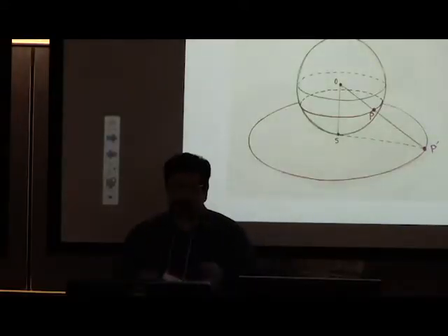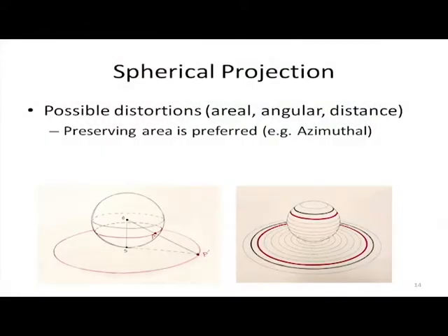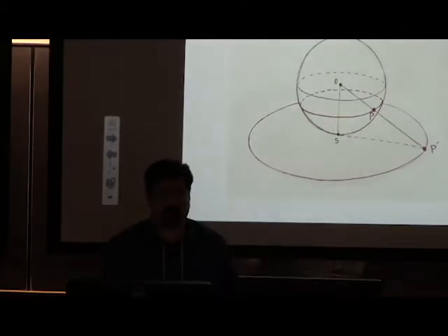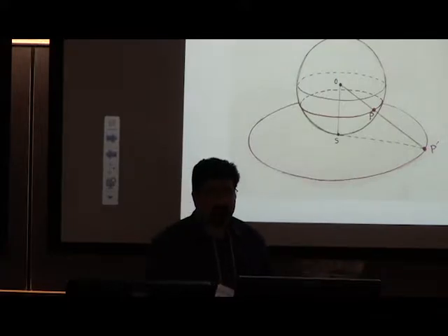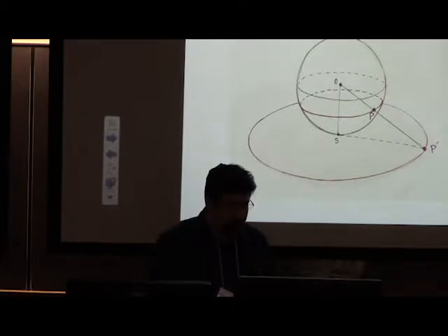So there is potential distortion of area, angle, shape, distance, and direction, and whatever 2D map you use, some of these will happen. There is no way to avoid that. But in the context of digital Earth, because cells are going to be placeholders for information, area preserving is the most important thing, because you want to use these cells later for statistical analysis, for getting integration of somewhere, to do simple statistical analysis. You need to have area preserving.